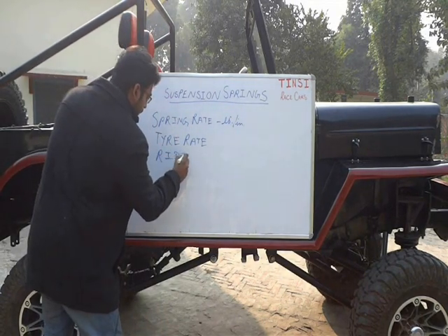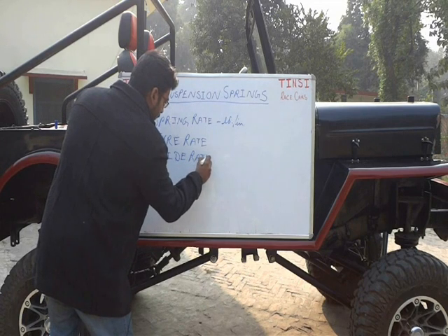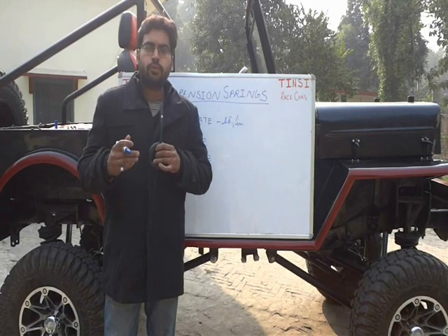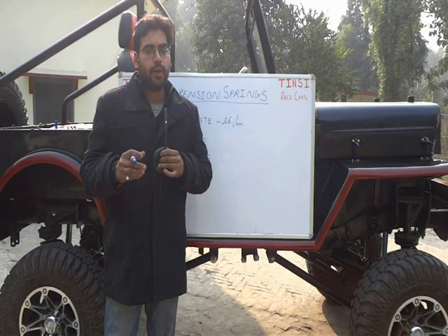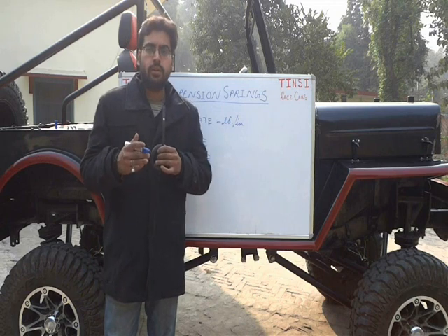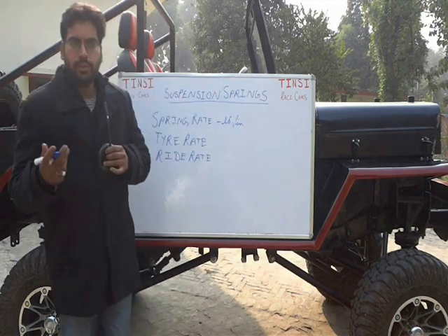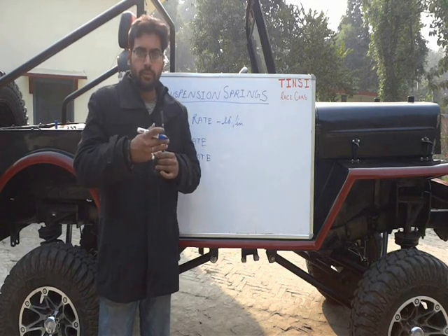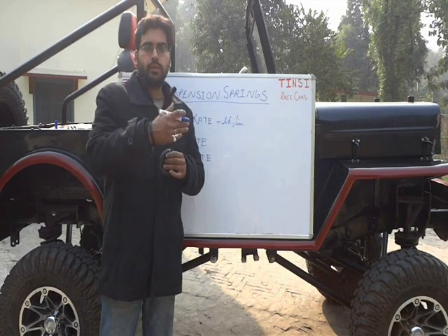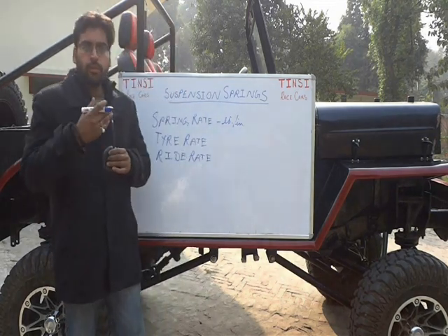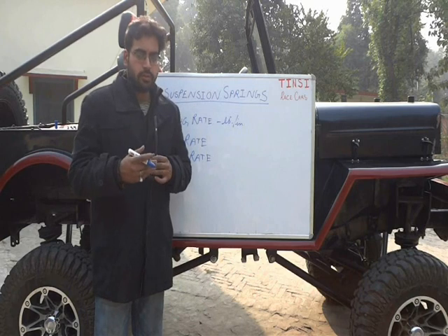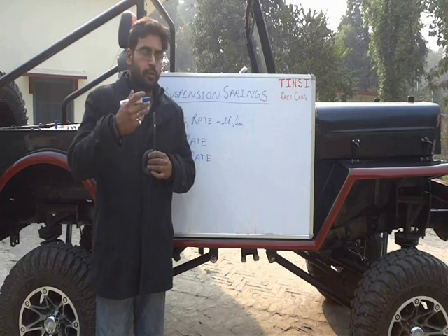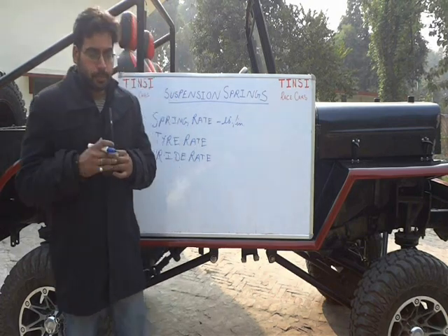Okay, so when we are going to the calculations of the springs, first we assume a particular value for the roll rates. Generally this is done through your experience. Okay, the starting of this is done through experience. There is not a set of defined parameters or formulas that give you the roll rates. So when we go into designing the spring, we start by giving a guess of the parameters that we need, meaning the roll rate. Okay, so it may be tough for you.